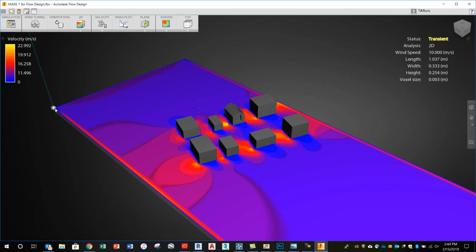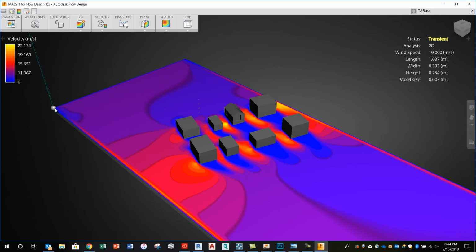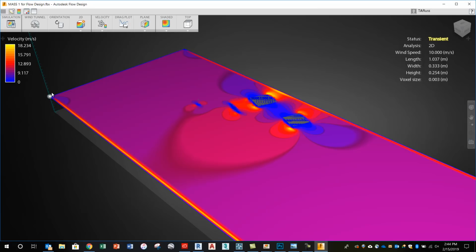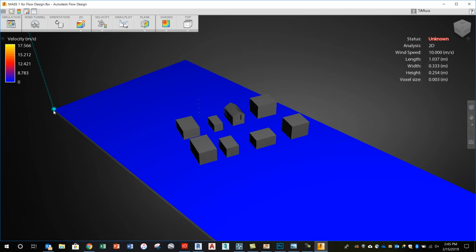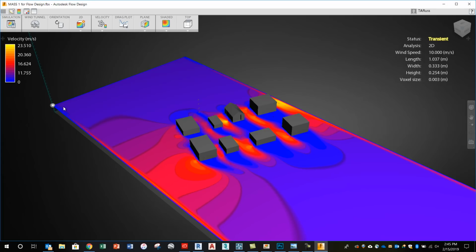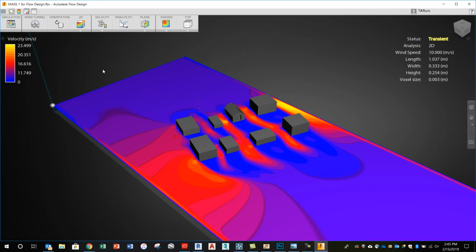And as for what vertical plane you choose to do the simulation at, that's your call. Just do it where there's maybe a little bit more turbulence, where it's telling you more about wind patterns around your building. This obviously up here doesn't do us any good. We don't want to see that. But we also don't want to see it right down at ground level either. Think about again where maybe you're going to have your occupants sitting on a balcony or a deck or something like that. And this will give you a feel for what the circulation patterns might be like around your building. Okay, and that's it. Those are all the steps of the first phase of this assignment.